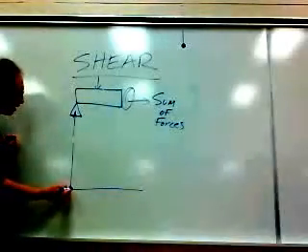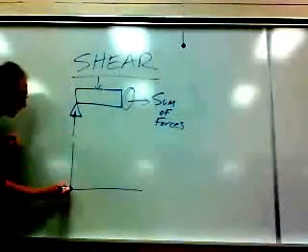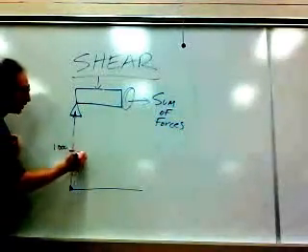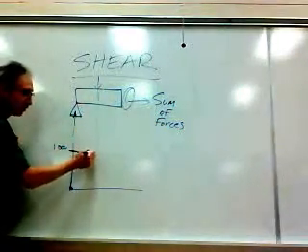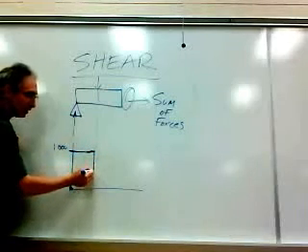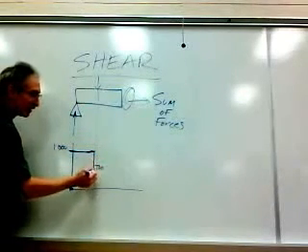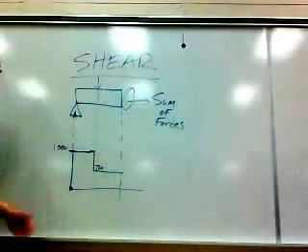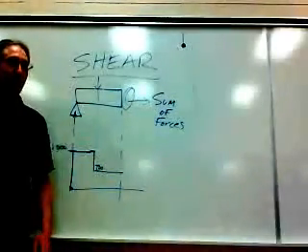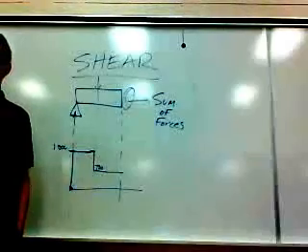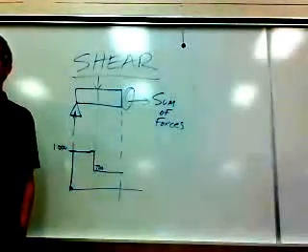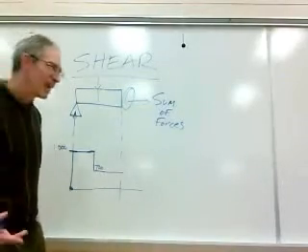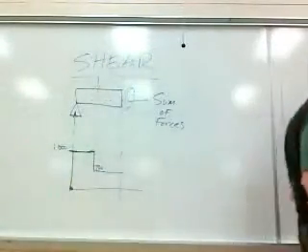If this was 1,000 pounds, I'd go up to 1,000, and then nothing would happen until I hit this load, and if this was 300 down, it'd drop me down to 700, and if nothing else happened up to this point, at that point I'd have 700 pounds of shear. Okay? That's what the shear diagram was all about. So that's what we did back in strength of materials.